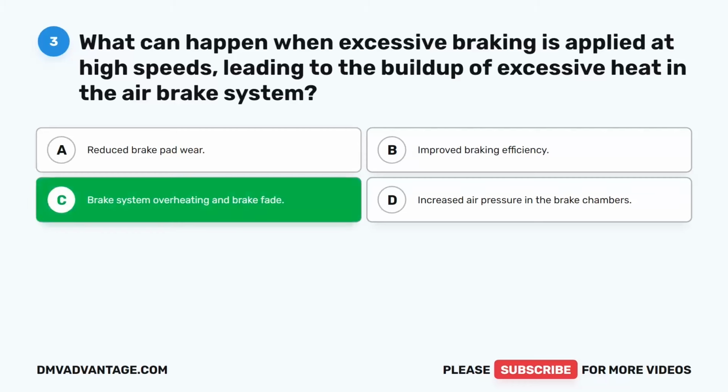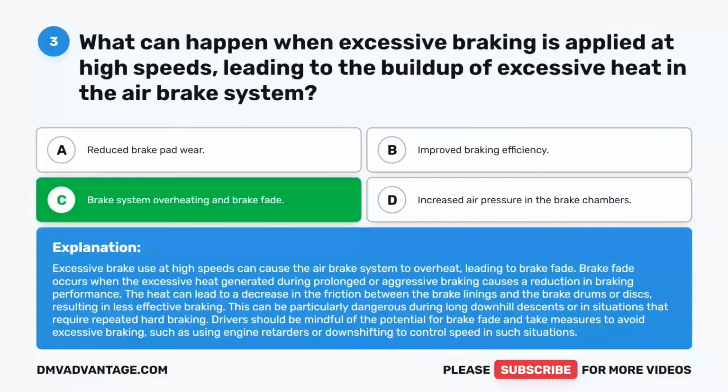The correct answer is C. Brake system overheating and brake fade. Excessive brake use at high speeds can cause the air brake system to overheat, leading to brake fade. Brake fade occurs when the excessive heat generated during prolonged or aggressive braking causes a reduction in braking performance. The heat can lead to a decrease in the friction between the brake linings and the brake drums or discs, resulting in less effective braking.